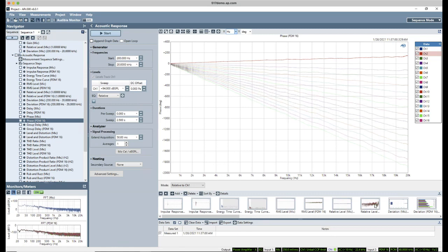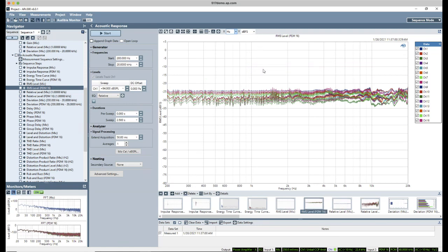And again, since I have calibrated the sound source to give us 1 Pascal at the reference position, I could, in theory, directly measure the sensitivity right here, right? Particularly if we look at channel 2, right? That is channel 2 is where the reference microphone is aligned to. So I can see, oh yeah, I'm getting right about minus 26 or 25 dBFS per Pascal.